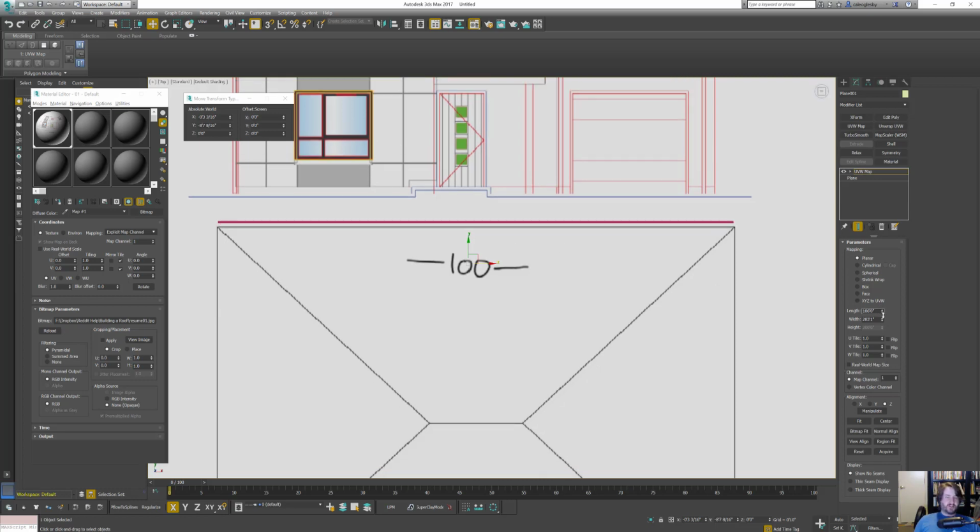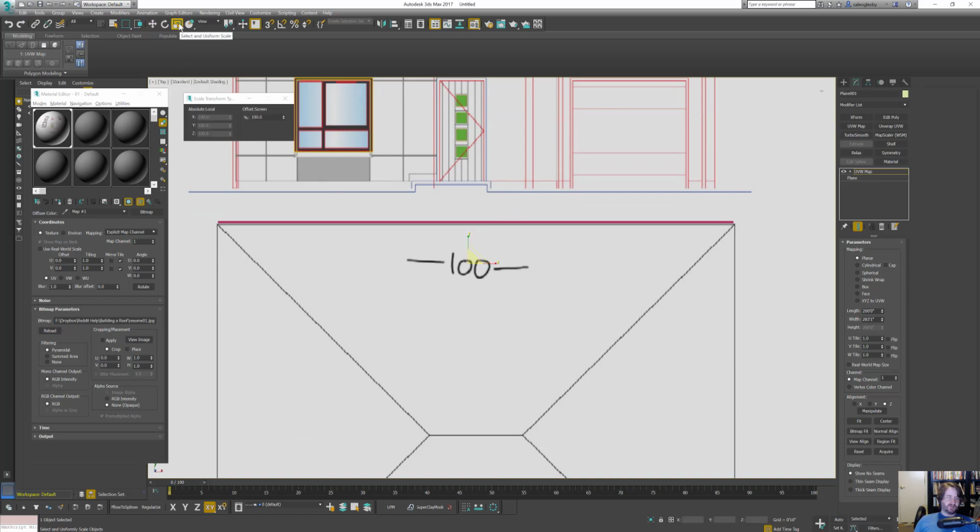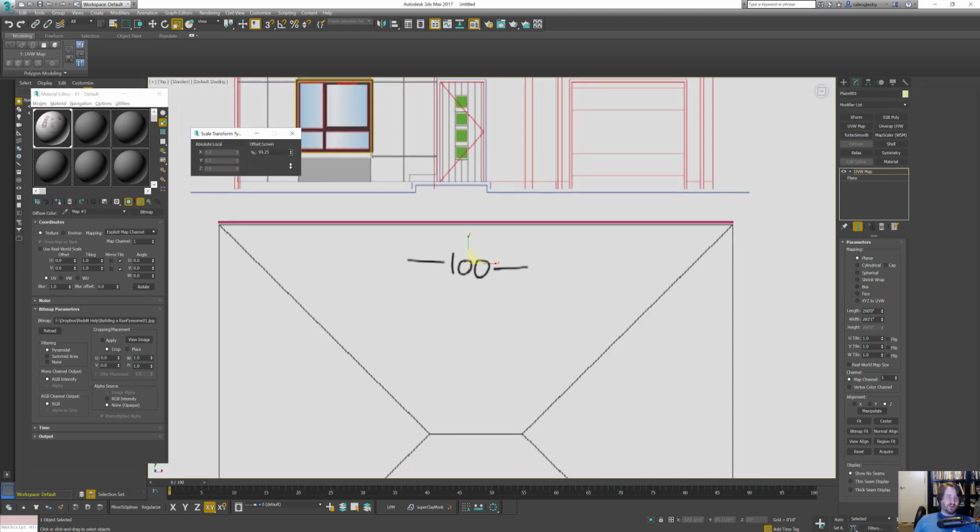And now you can adjust this, but you can see that you're squashing it again. So the only thing you can do is scale it. So if you right click on the scale, it brings up this dialog, and then if you hold down the Alt button, you can get incremental scale, and you just want it to be about the size of this box.